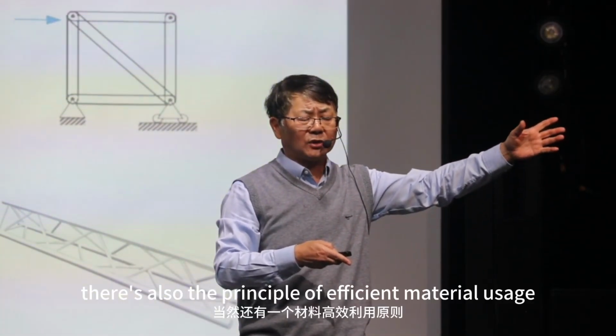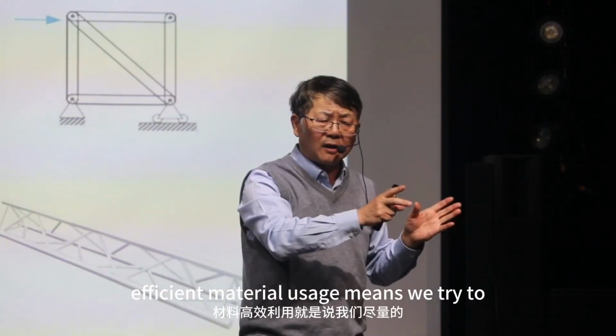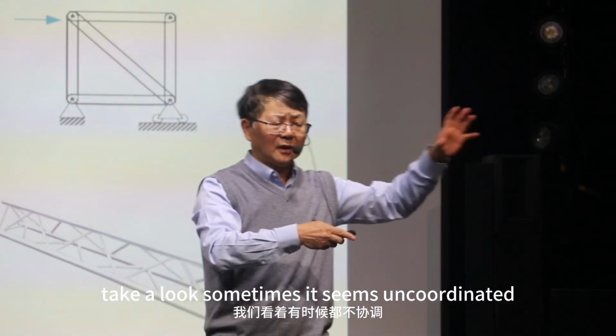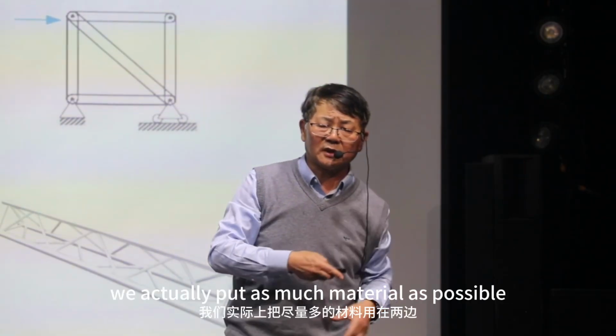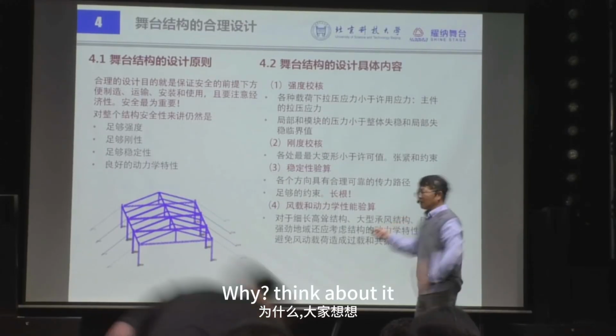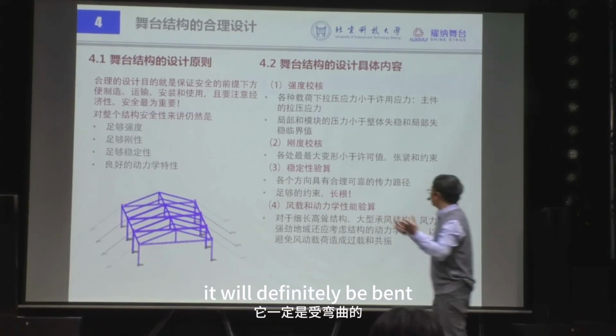Of course, there's also the principle of efficient material usage. Efficient material usage means we try to... take a look. Sometimes it seems uncoordinated, like these rods. We actually put as much material as possible on the two sides. Why? Think about it. If this beam is placed horizontally, it will definitely be bent.